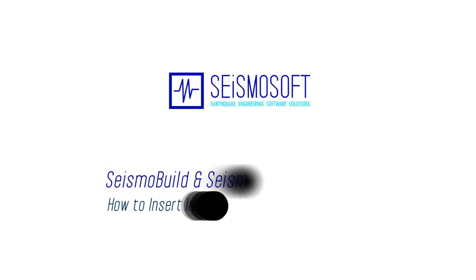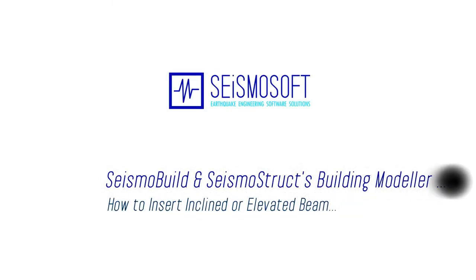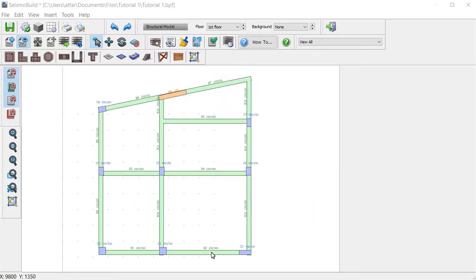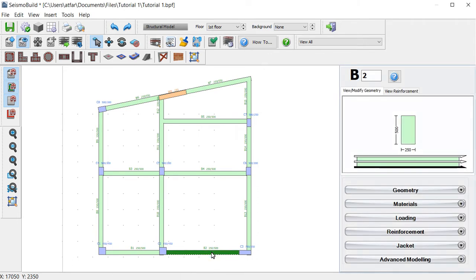This is a quick tutorial of how to insert an inclined or elevated beam in SeismoBuild and SeismoStruct's building modeler. First, we select the beam B2. And the section properties window will appear on the right part of the building modeler window.